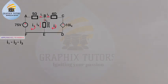Everything equals 0. That is the Kirchhoff current law. Now if I make I3 the subject of the formula, I3 equals I1 minus I2. And this is the same thing as saying Ix. So my Ix is the same thing as my I3.